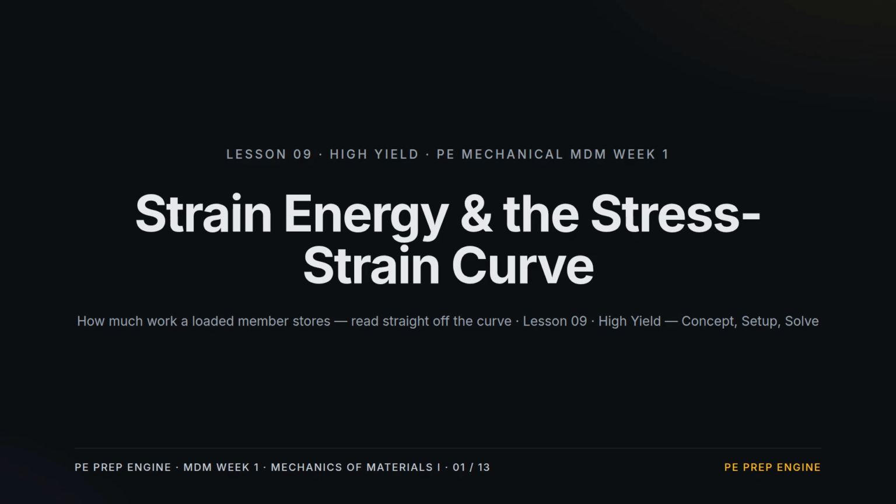Lesson 9. Strain energy and the stress-strain curve. Every time you load a member elastically, it stores the work you put in, like a spring. That stored work is the strain energy, and it's just the area under the load deflection line.